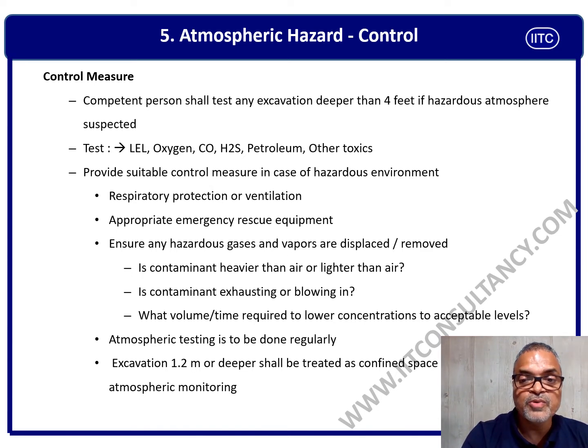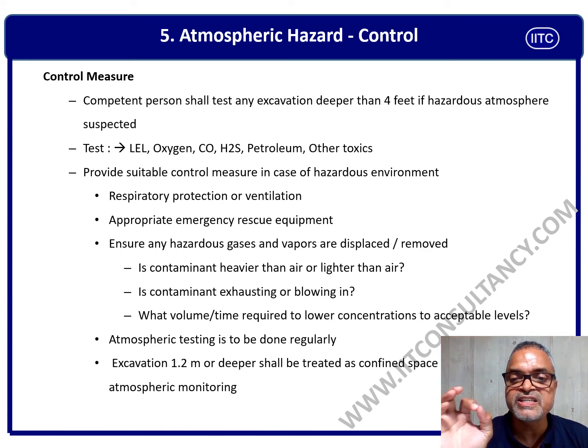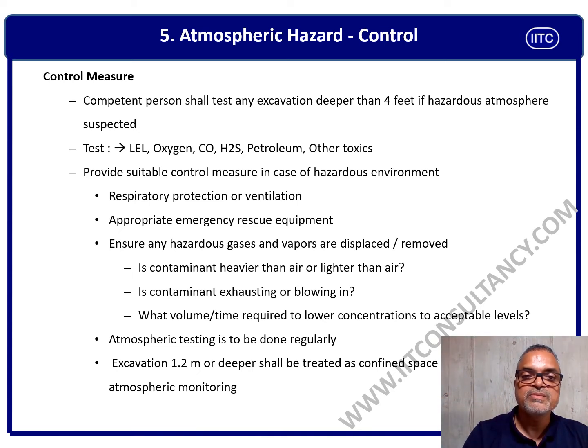Any excavation 1.2 meters or deeper shall be treated as a confined space. This has been discussed earlier, and we have a separate, very good program for confined space entry. I urge you, after this program, to please go through the training program on confined space. You will get each and every piece of information crystal clear so that you can educate yourself, your team, and your fellow members. This is very important to protect us from the toxic hazardous environment in terms of excavation.